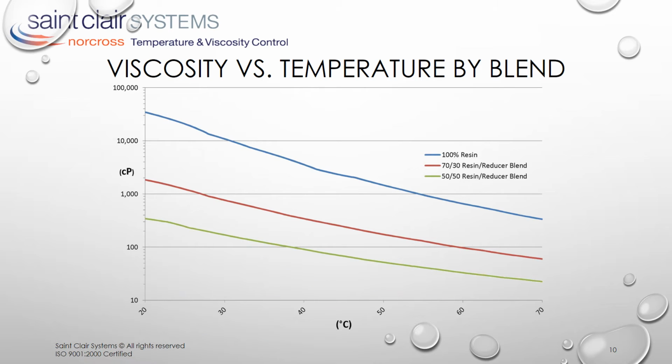To demonstrate the similarity between the characteristics of solvent-borne, waterborne, and 100% solids coatings, we will make the assumption that we are substituting this 100% solids coating for the solvent-borne coating above in the same application, and therefore desire to have the same 26-second viscosity. A viscosity conversion chart reveals that 26 seconds in a Zahn 4 cup is equivalent to about 325 centipoise. If we look at 325 centipoise on this graph, some interesting coincidences appear.